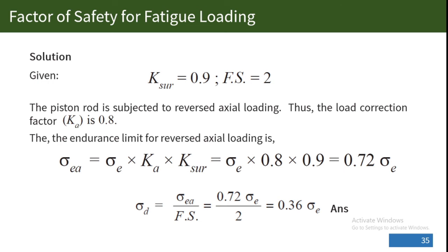And next, we discussed the different factors that affect the endurance limit. What are these factors? The load correction factor or the load factor, surface finish factor, the size factor, and the miscellaneous factors such as the reliability factor, temperature factor, and the impact factor.